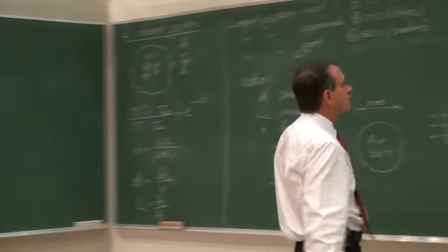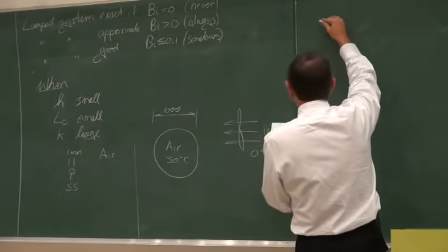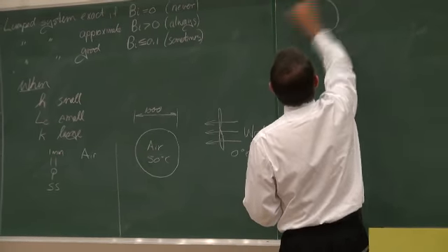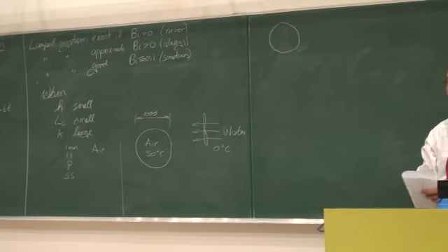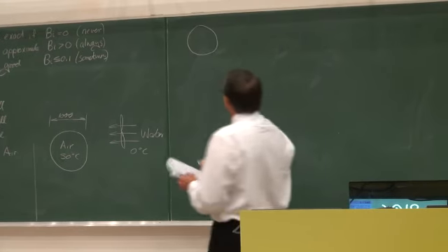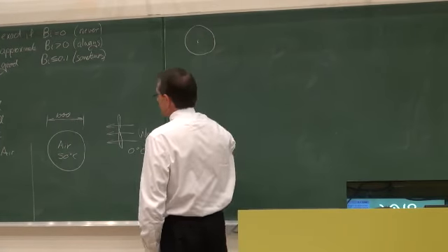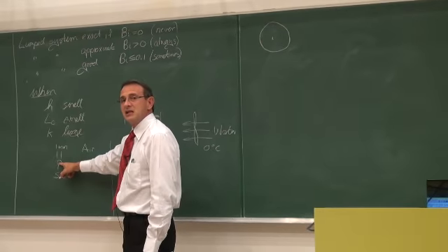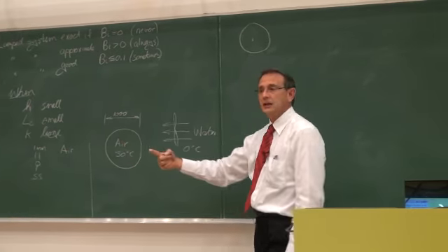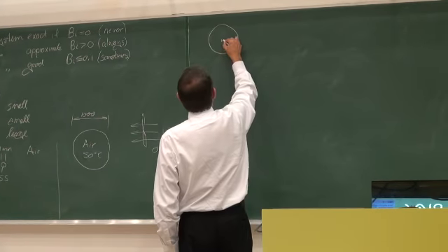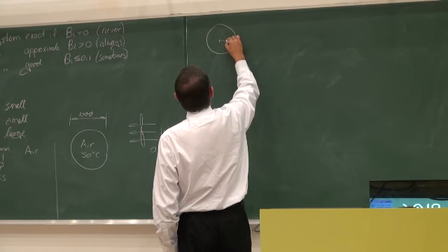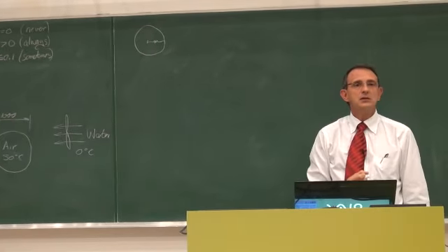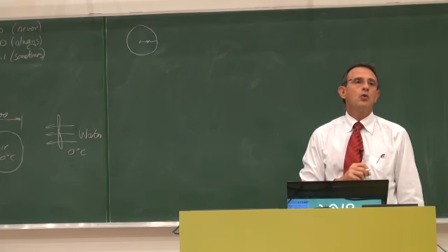Now let's look at the first one, the ball bearing. I'm going to make the ball bearing a little bit larger now. Because we've got stainless steel, and stainless steel has a high thermal conductivity, the resistance term inside the stainless steel is very, very small.